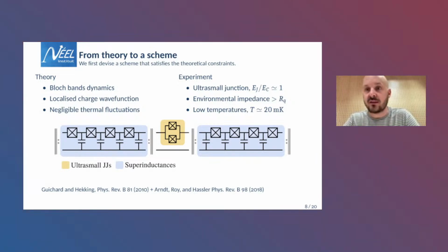And it makes sense. I could give you a full derivation, but we can use a very simple hand-waving argument. If you put a very large resistance in series with your tunnel junction, it will be difficult for the charge to tunnel. So you have something like a Coulomb blockade, if you wish. Again, it's hand-waving, but it's kind of a Coulomb blockade. So you can tunnel charges one by one only, if you wish. So this is the hand-waving argument for why you need very high impedance.